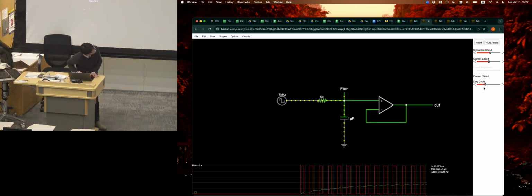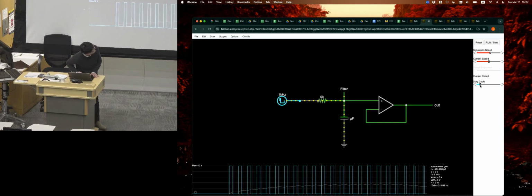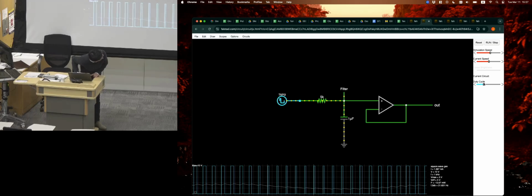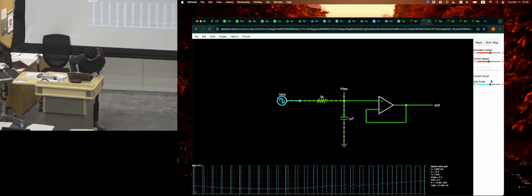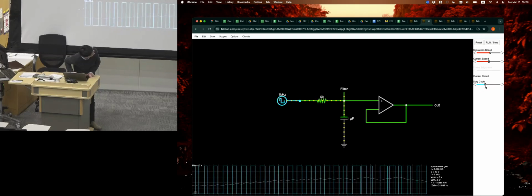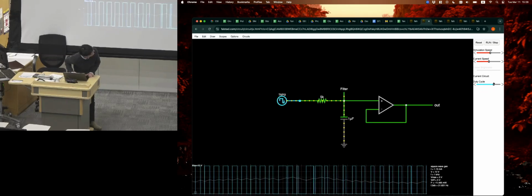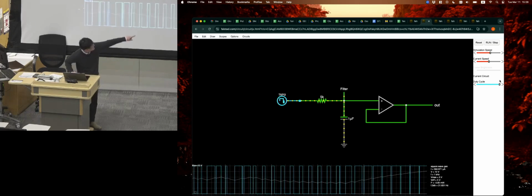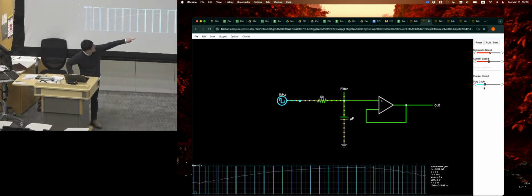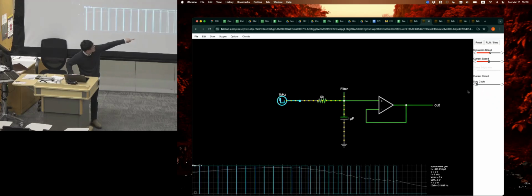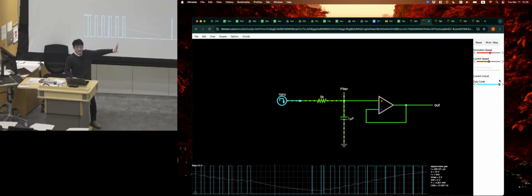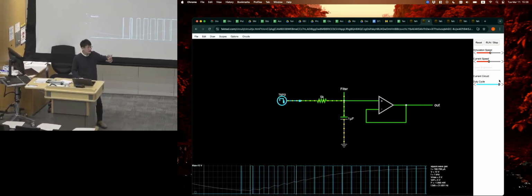Okay, so imagine if, say, we start from here, and then I gradually increase. Is it going anywhere? You'll see a little tendency of going up, and then once we reach that, it's gradually going down, and if we do this very fast, that's essentially the idea behind this PWM triggered, or PWM plus low pass filtering.